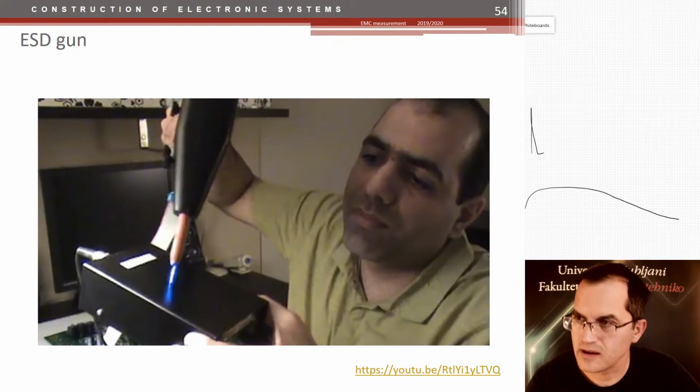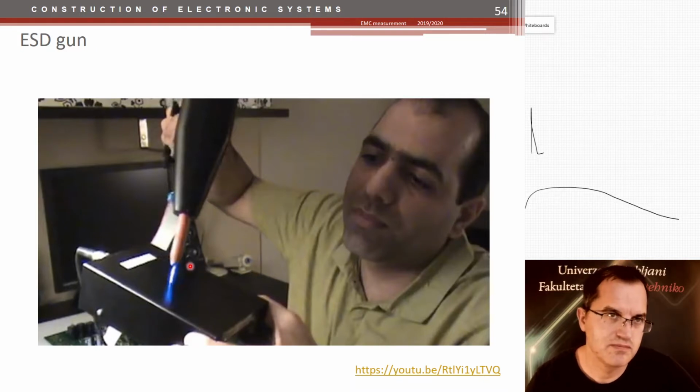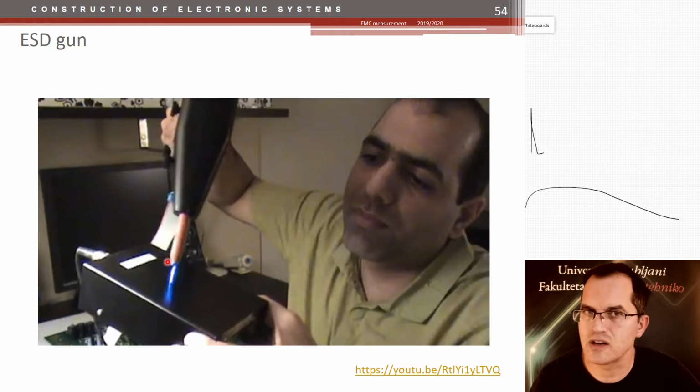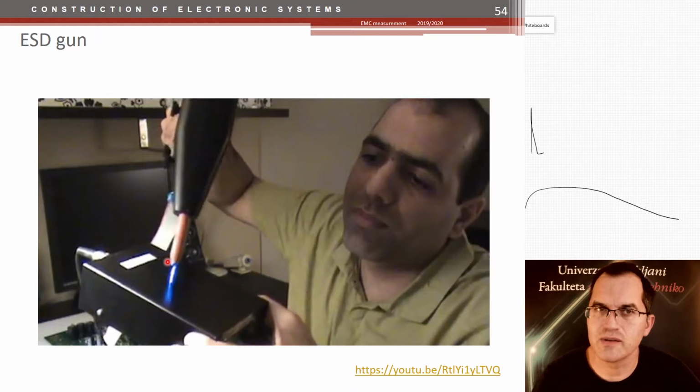Now, discharging looks like that. That's a guy who likes to try things. You might have already seen him on YouTube. So this is how the discharging looks. As I said, you can discharge in the housing or not, depending on what type of test you're making. Just bringing the gun closer to the device without the discharge can already cause a reset of the microcontroller, for example.